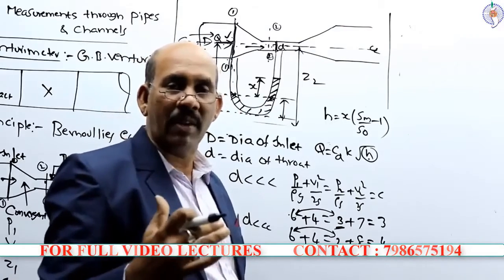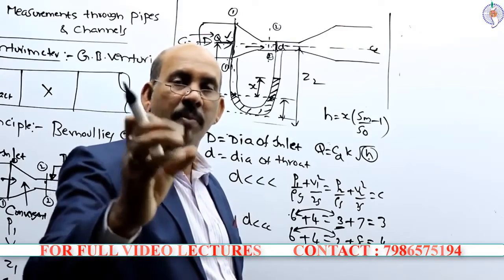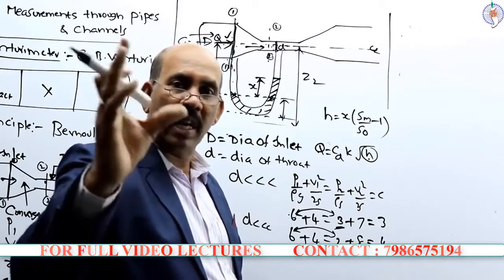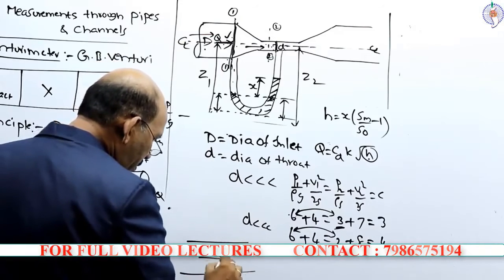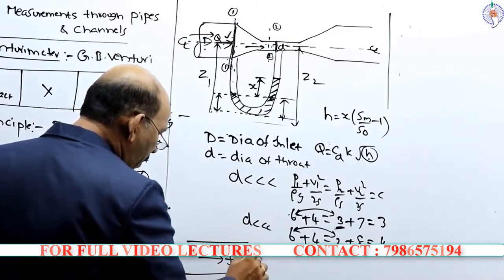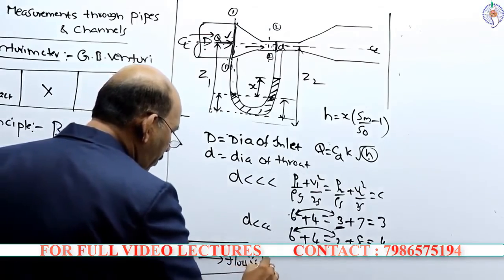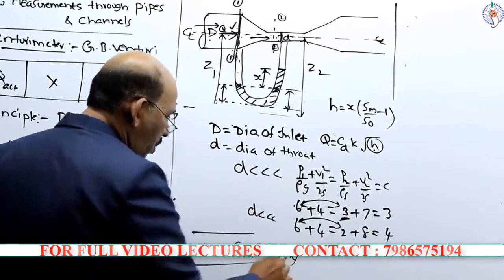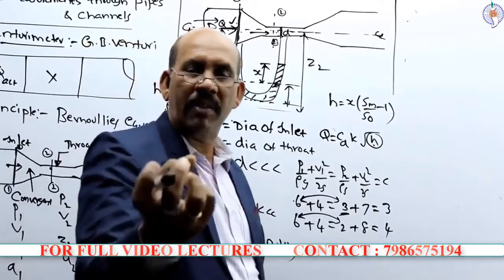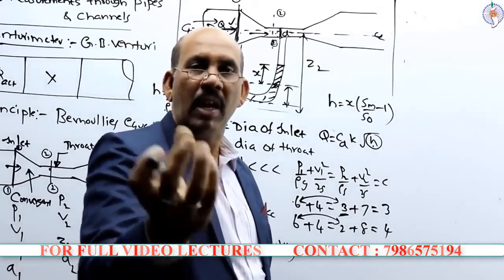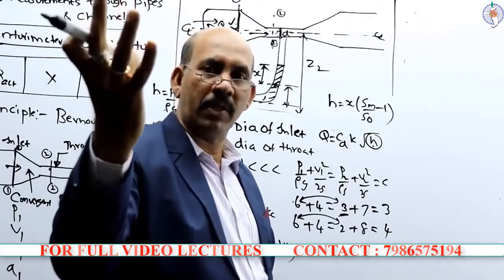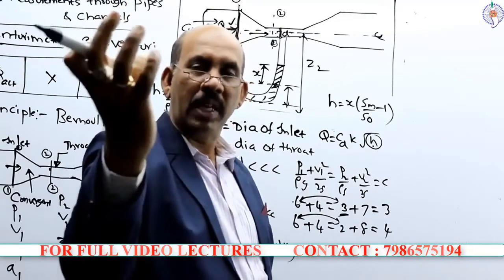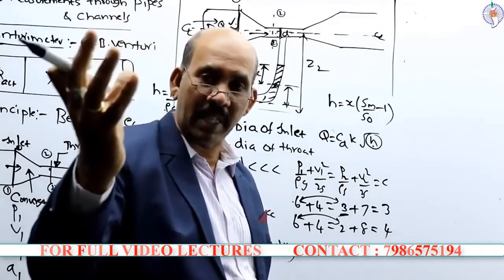Once the suction pressure develops, this suction pressure forms the bubbles in the liquid. That means when the flow is taking place, the bubbles will form in the liquid, and these bubbles will not continuously form. The bubbles will form and the bubble will burst. Once the bubble bursts, it exerts very high pressure.